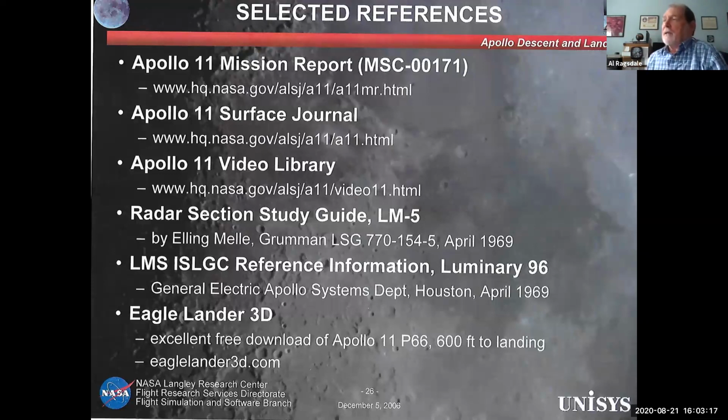For example, when Apollo 11 docked, they weren't quite lined up. You want to come in straight, and he was misaligned about 15 degrees when he bumped that collar that was supposed to dock them. They were both in attitude hold. So both vehicles were trying to hold their attitude, and it did this for a few seconds with all the jets firing before he realized what was happening and turned the attitude hold off in the LM. So when they got back, one thing we had to do immediately was put in a mod to simulate misaligned vehicles.